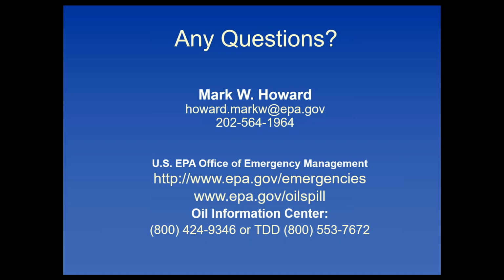We have a question about whether the rule applies to gas pumps at county-owned facilities. Yes, it does if it's otherwise subject. So what that means is if you have over 1320 in aboveground storage tanks that may be attached to a dispenser, yes, the transfer to the vehicle, even though the vehicle wouldn't be counted because of motive power, the transfer would be regulated if you break the threshold. The good news is general containment, typically a spill kit, can take care of that.